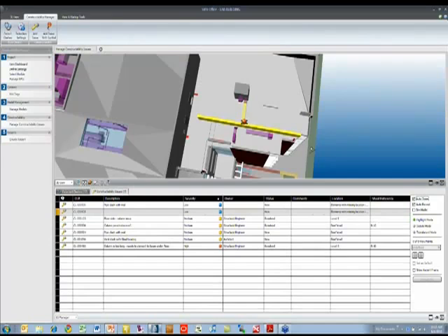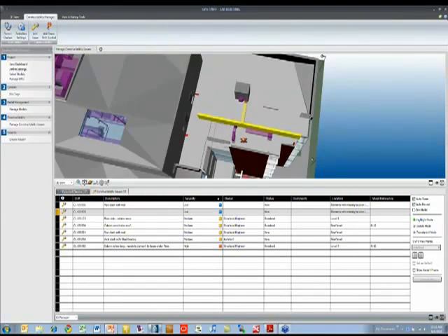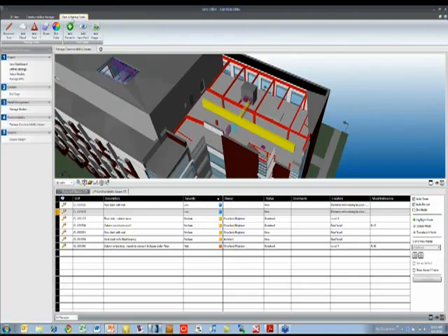We go to auto zoom, and we can see where the item is. And then we can start to actually analyze the issue and mark up a view of that item. So we can add a viewpoint, and then we can start to add, for example, a cloud around this, so we can show where the issue is, and then, for example, add a freehand. This is where it is, point to it even. And people can understand it and save different viewpoints, and we can roll through those viewpoints. And these are the viewpoints that will then be reported in our report that I showed you before.